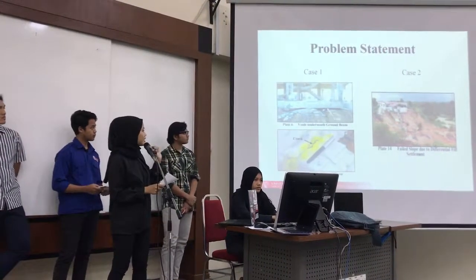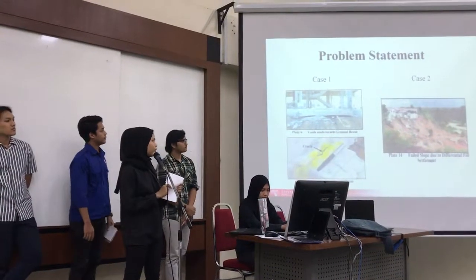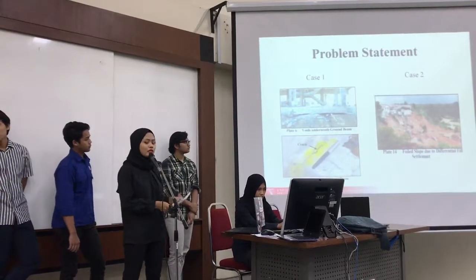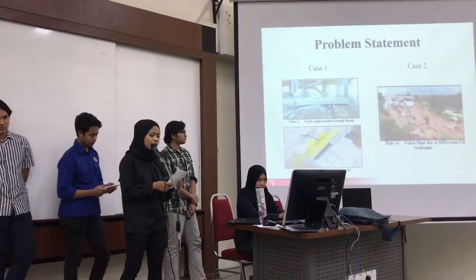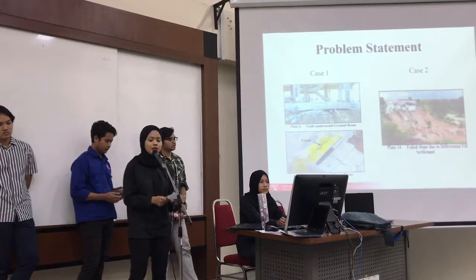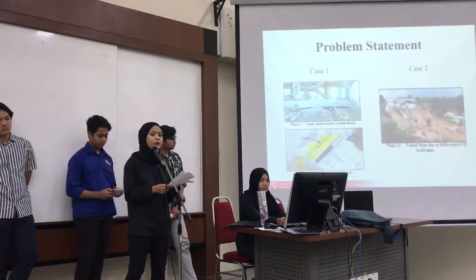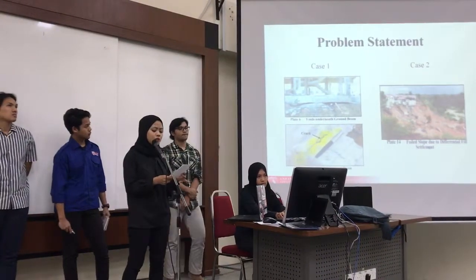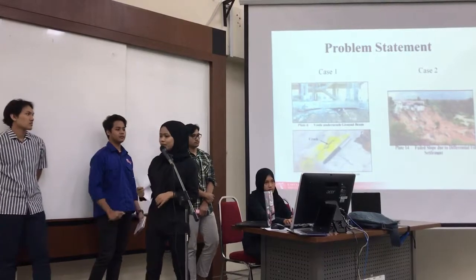These are examples of the problems that occurred on that project, which involved voids underneath the ground beams and also cracks on the ground beams. The second case is the distortion of the building, where it involved excessive distortion of the two-story terrace structures. This is because of the uneven settlement of the platform across the longitudinal axis of the structures. Tension cracks also occurred on the structure frames and walls built around them. Lastly, it occurred because of leaking water, which subsequently caused the fill material to collapse and led to the distortion. Next, I will pass the presentation to Jazmi.